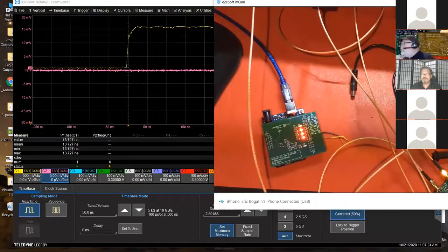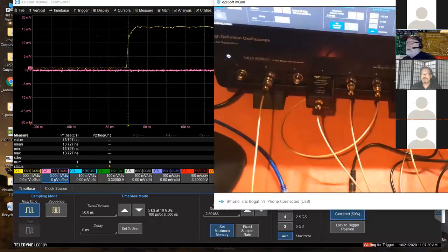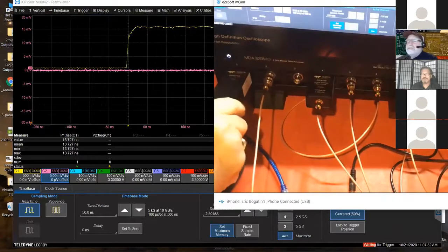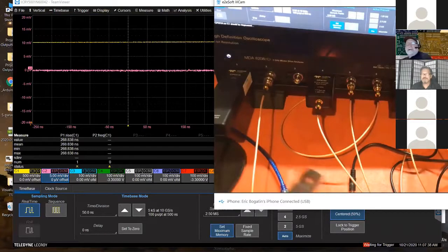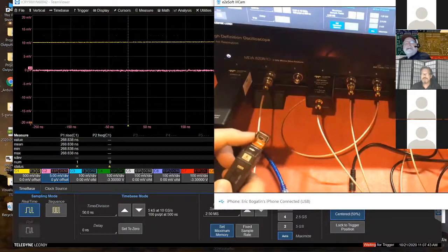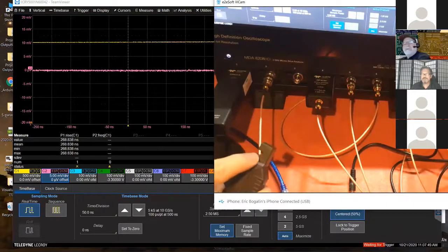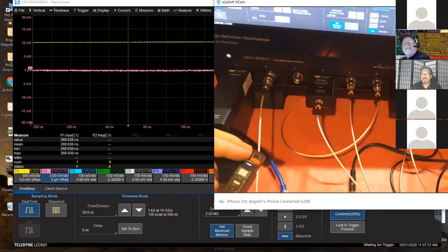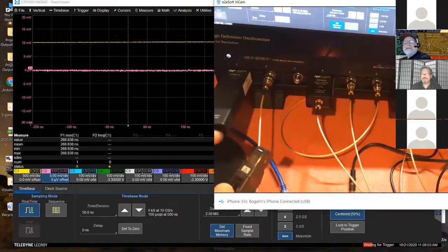So I'm going to show you again my setup over here. This is one of our current clamp probes. It's really a Hall effect probe. It's a current clamp, and on the inside here, it's got a ferrite core, a high permeability core. Any current going through the probe generates a magnetic field that is accentuated by the ferrite core, and there's a Hall effect sensor in the middle of it measuring that magnetic field. That means that even DC currents that generate magnetic fields, we can measure.